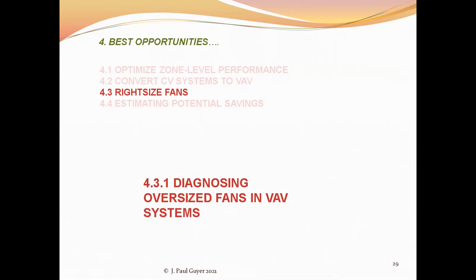Has the utilization or occupancy of the building changed since it was first designed? Has some equipment been taken out, some equipment brought in, more people moved out, more people moved in and moved around in the building? And all of these things can reduce the load on the system and therefore reduce the load on the fan. So right sizing the fan is an opportunity.